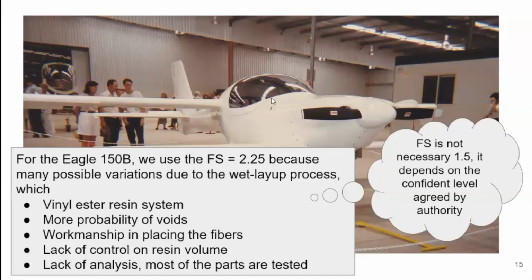And also the Eagle is still the Eagle. We do not do complete analysis. We have not done thorough analysis, and basically we build the part and we test, and build and test, and as we are satisfied, that is the part that we use on the aircraft. So it's basically a very conventional way. It's not using highly software tools for the analysis. So we are using test, most of it by test. So this variation ends up with us using a higher factor of safety.